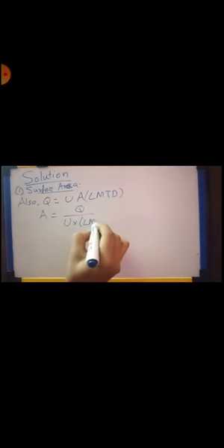There is another equation also for heat transfer Q. It is Q is equal to U A LMTD. Therefore, A is equal to Q divided by U into LMTD.